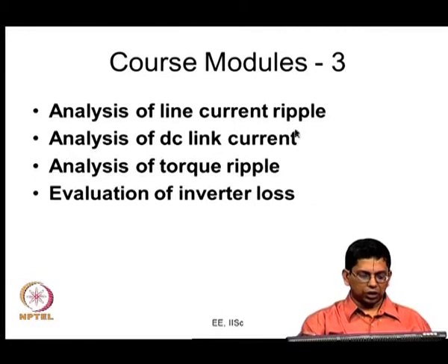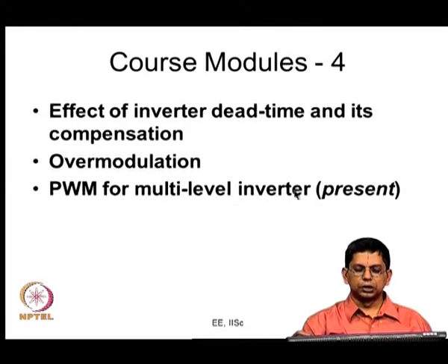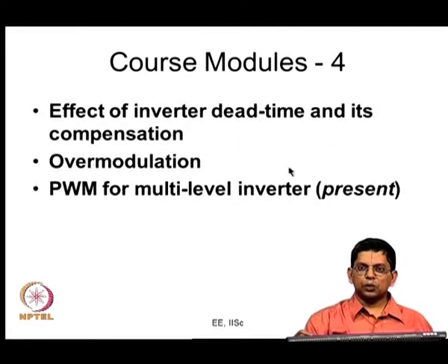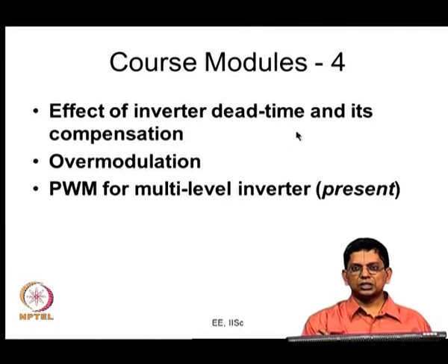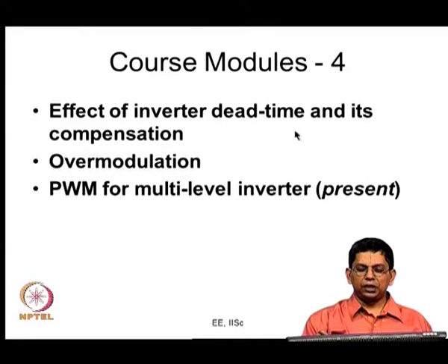Again, these are all in the context of 2-level inverters, and mostly they could be extended to 3-level inverters. Then here we looked at certain advanced issues, for example inverter dead time. Because the switching transition takes a considerable time, we introduce this dead time, that is we are not switching the 2 devices in a leg exactly complementary, we delay the incoming device.